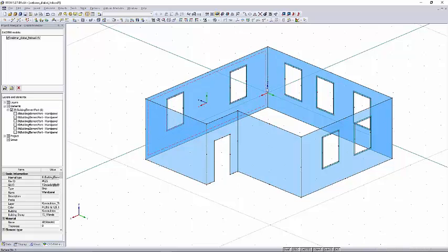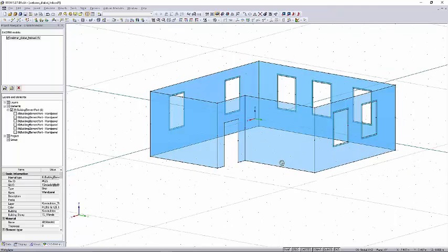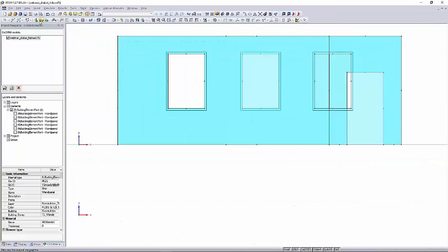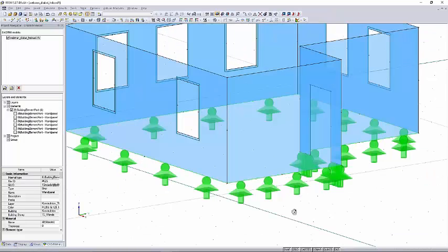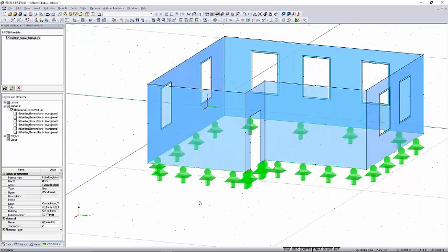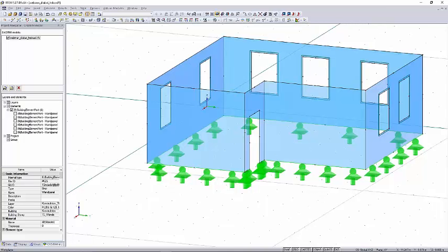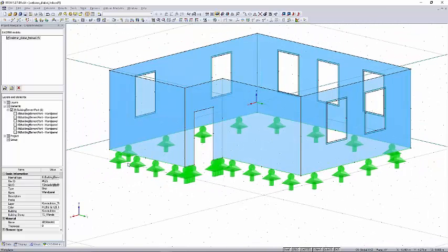It has no material right now, and all the corners are moment stiff for the rotation. These are things I must look for right now. The first thing I will do is to add some support to the structure. I will just create a linear support fixed in all directions. There are a lot of other webinars and videos where it is explained in more detail what to do with the CLT construction or what points you should look for. We are not catching that so detailed now in this webinar, so that's going to be rather a rough implementation of it.